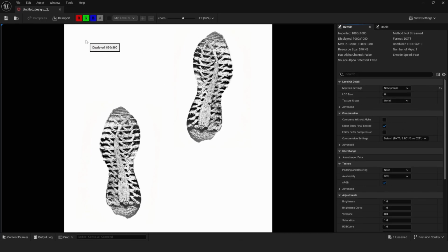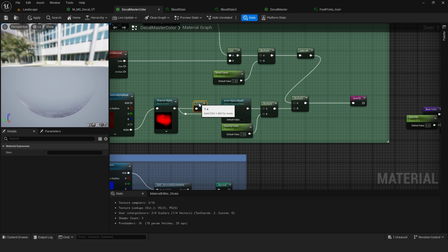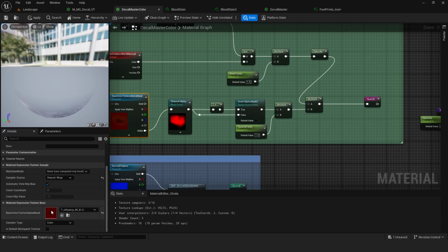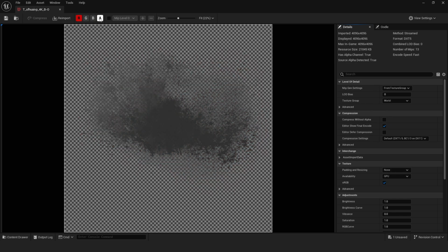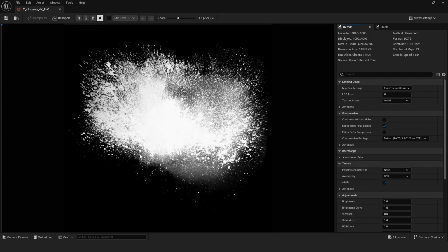Since if we open this, we want this map to be the alpha channel, except we want the black color to be displayed and the white one to be hidden. And that's also a reason why we have this switch, to invert the alpha channel or not. Normally, I apologize if this is confusing, I'm not explaining myself properly. If we go to this texture, which is the one I downloaded from Fab, the red channel has the height map. Red, green, and blue contain the color of it itself. And then the alpha channel contains the alpha mask.